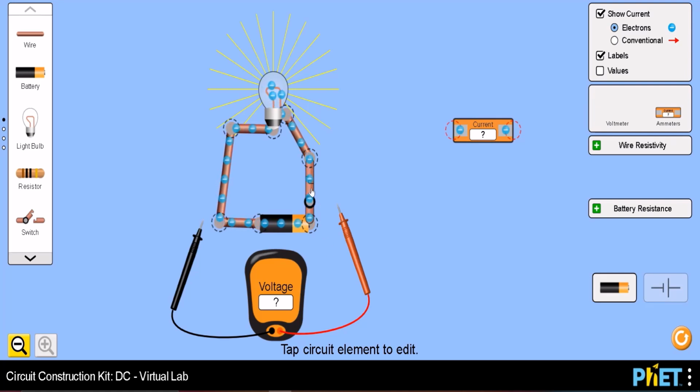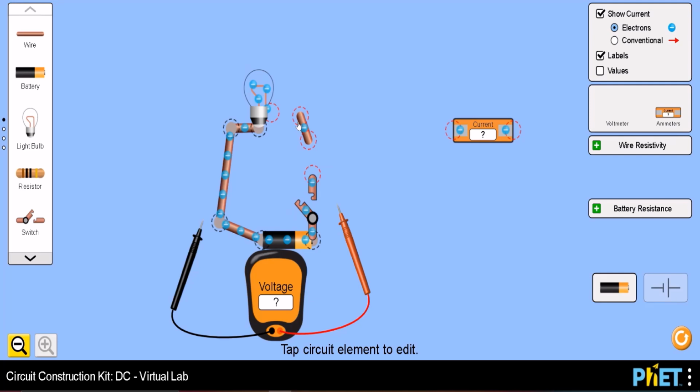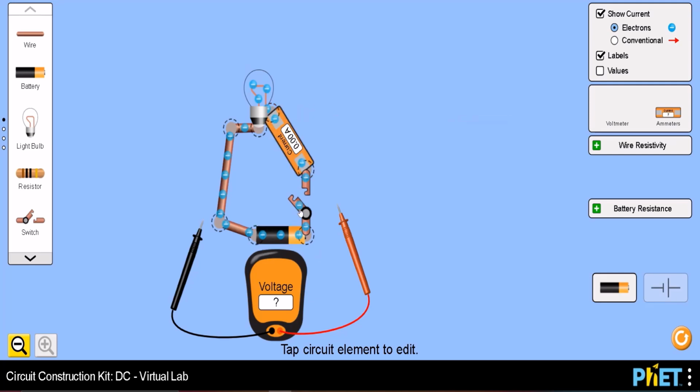So let me first of all open the circuit so that the current stops flowing, and then I will replace this wire with the ammeter. So let me join the connections once again, and the current which is now flowing through the bulb is 0.9 ampere. The 9 volt cell is right now providing a current of 0.9 ampere, and the bulb is glowing.